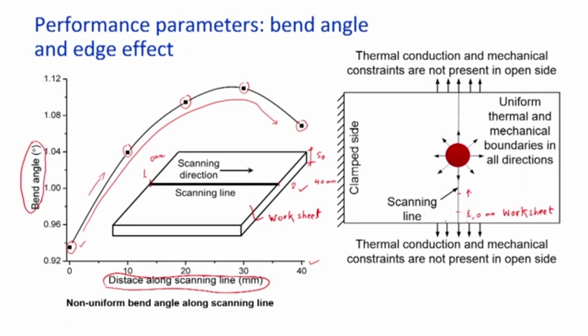When there was a spot over here, there was a bending occurring. Due to this bending, some energy was getting dissipated inside the work part. So, the next location was getting the benefit of heat flux from the previous location of the laser beam. There was a preheating of the subsequent place, and that preheating was helping to get more bend angle. So, that was noticed for further increase.